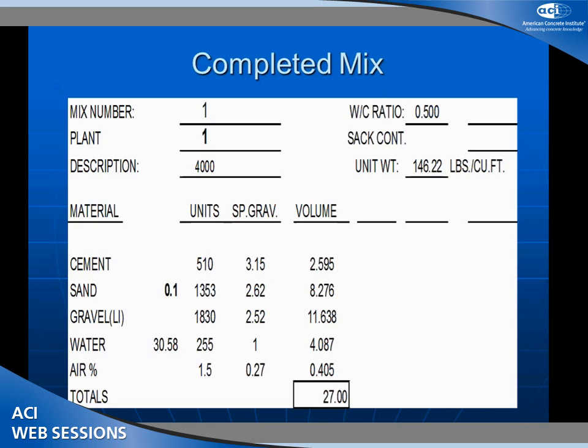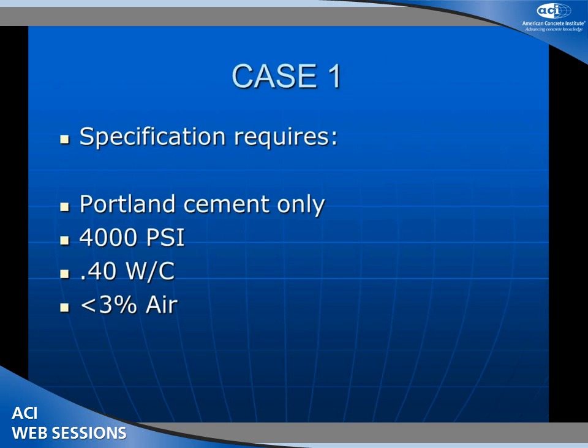This is a standard 4,000 PSI, 28-day mix, about 510 pounds of cement, sand, gravel, and water. Water demand there is about 30-plus gallons to get a 4-inch slump out to 90 minutes in the summertime. This is a plain mix right now. We'd ordinarily have retarder in this.